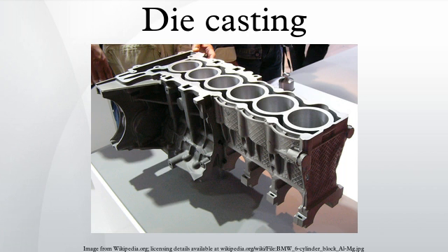Process: the following are the 4 steps in traditional die casting, also known as high-pressure die casting. These are also the basis for any of the die casting variations: die preparation, filling, ejection, and shakeout. The dies are prepared by spraying the mold cavity with lubricant. The lubricant both helps control the temperature of the die and also assists in the removal of the casting.